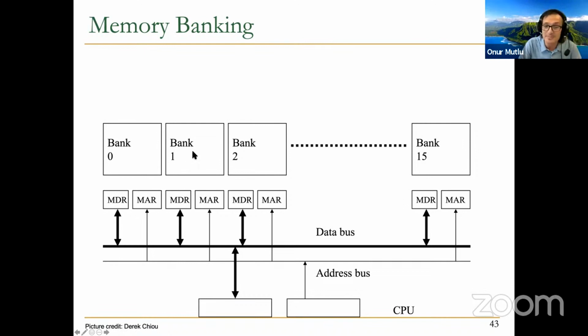The next element comes at the next cycle. The next element comes at the next cycle. So by starting the accesses in consecutive cycles, you're going to get the data n cycles later in consecutive cycles, right? That's the idea, basically. You sustain 1 element per cycle throughput, even though your bank access latency is more than 1, but you have enough banks so that you never have a gap in your throughput. Basically, you always get 1 access per cycle.